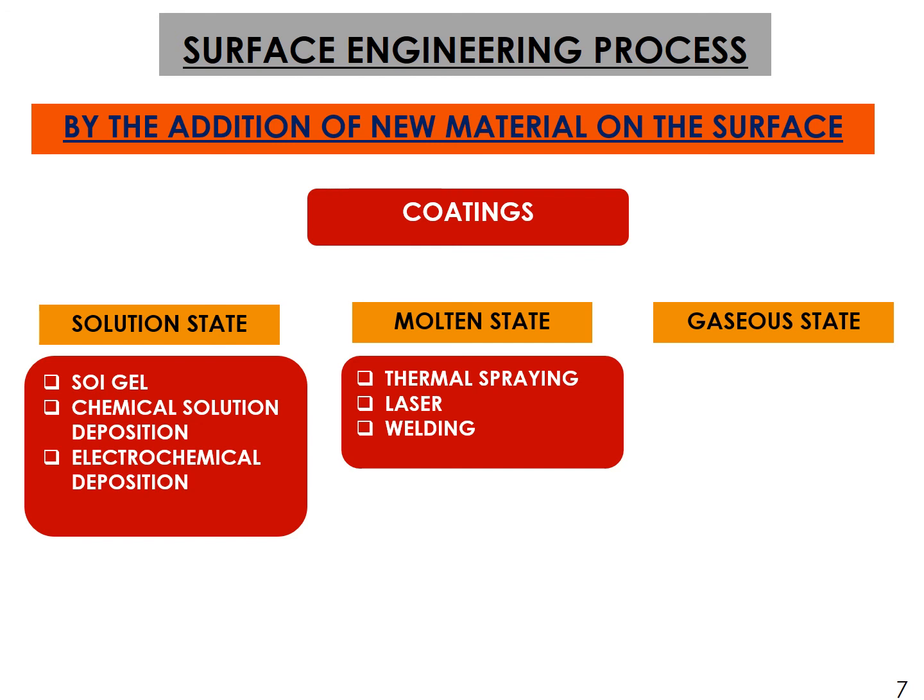You can see that the composite has superb wear and frictional properties. In spite of developing a new bulk material, I am just using some of that new composition and providing a coating to the mild steel. That way my job is done, and it is quite cost effective also. Yes, we have to check the compatibility of the substrate and that of the composition, so that they adhere to the surface.